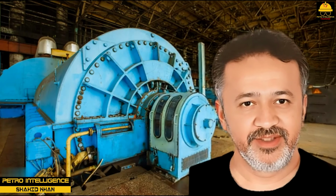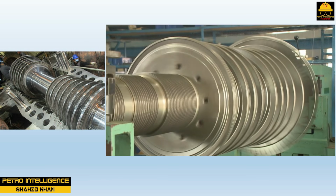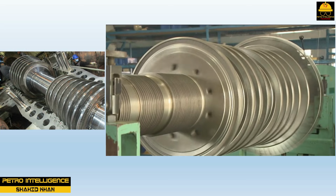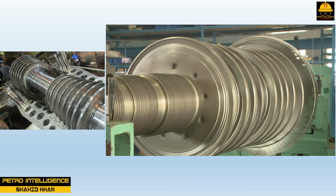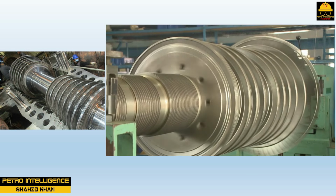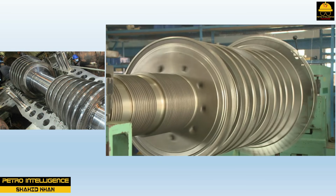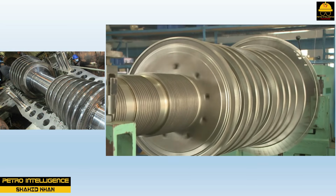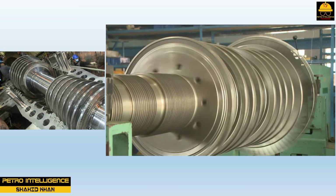Rotor. Steam turbines have a set of rotating blades and a row of fixed half-moon blades. The wheel-shaped rotating blades sandwich the fixed blades. Operators commonly refer to the assembly consisting of the shaft and the rotating blades as the rotor, as shown in the picture. A visual inspection of the rotor reveals that the rotating blades are firmly attached to the shaft. The rotor is statically and dynamically balanced to ensure smooth operation.